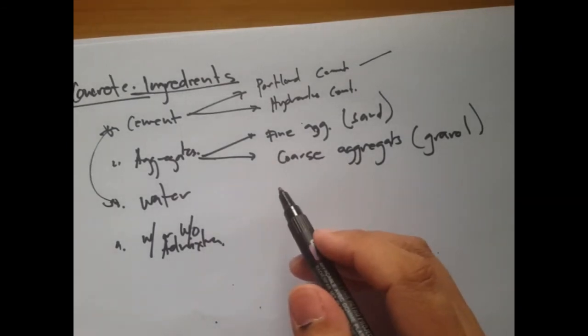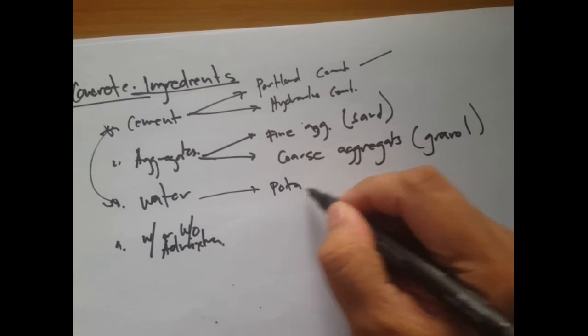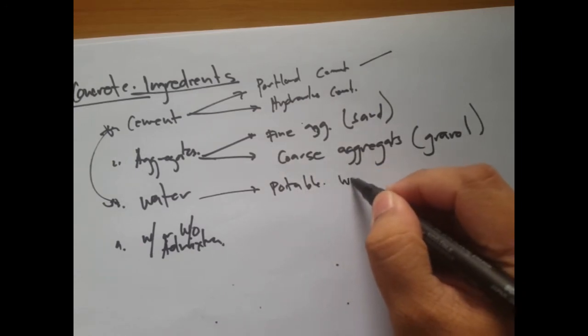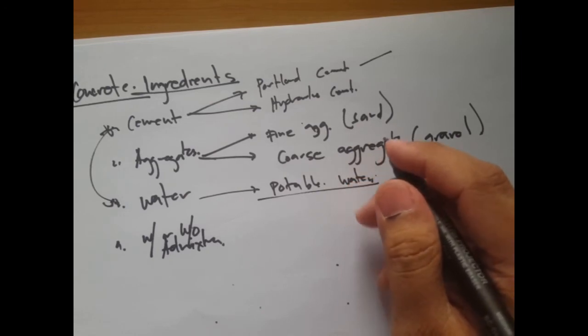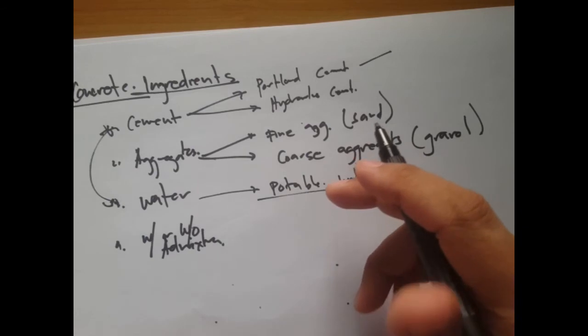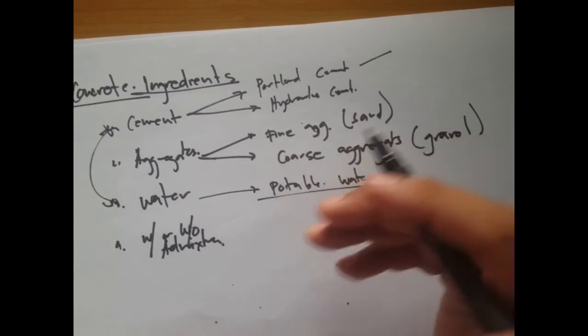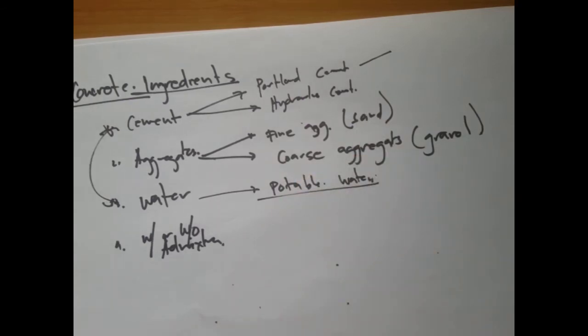For water, any potable water will do. Just refrain from the use of, let's say, salt water, because salt can corrode the steel materials, the reinforcing bars.